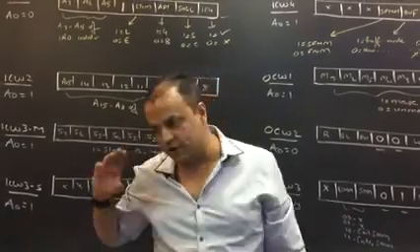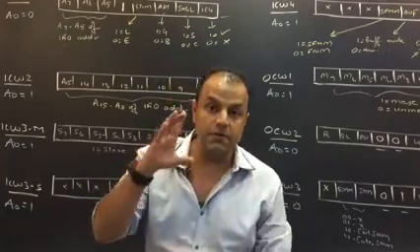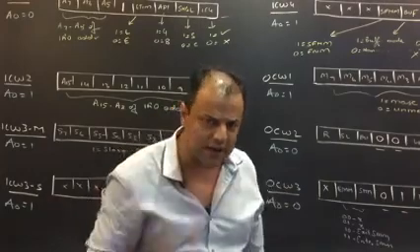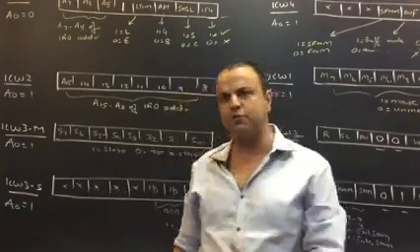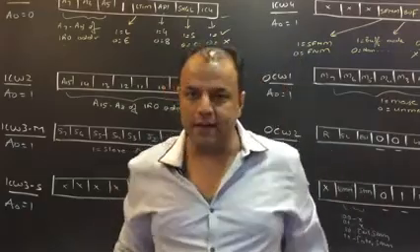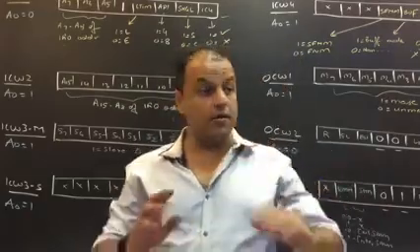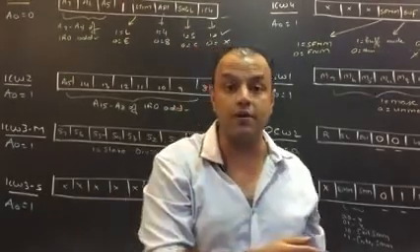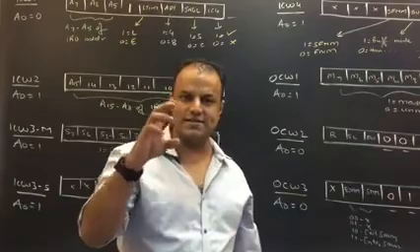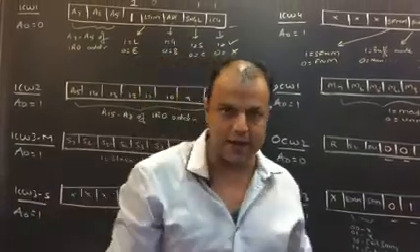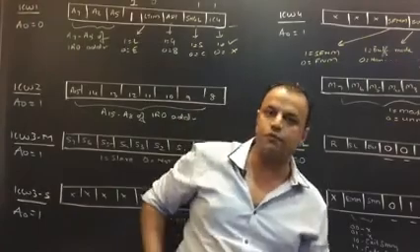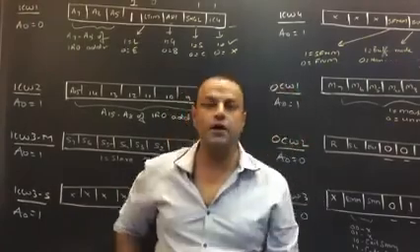So a gap of 4 is fine, but if you want, you can also keep a gap of 8, which is typical of 8085. In 8085, between interrupts there are gaps of 8, which you also know: 24, 2C, 34, 3C. That's not because they are rhyming. There's a gap of 8, and that gap of 8 is so that, apart from call and return, if there's anything you want to do before calling the ISR, like push some register in the stack, you could do that extra operation. So that's why they've given you an option of 8. That applies over here also. You can keep a gap of 4 or a gap of 8, whatever you prefer.